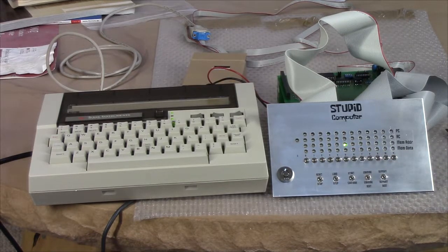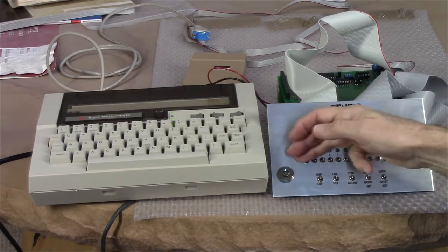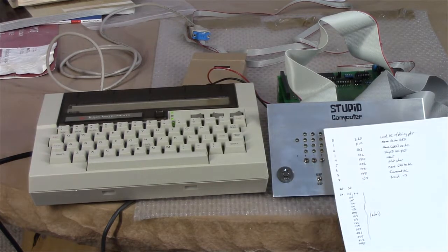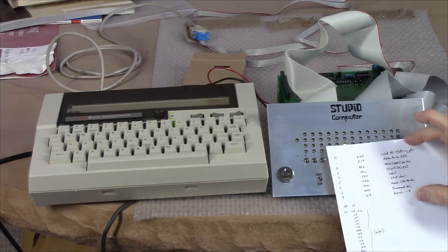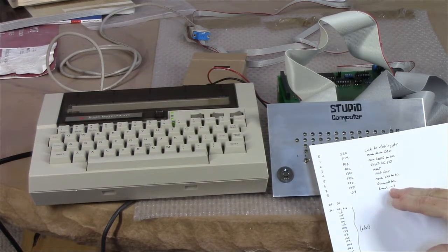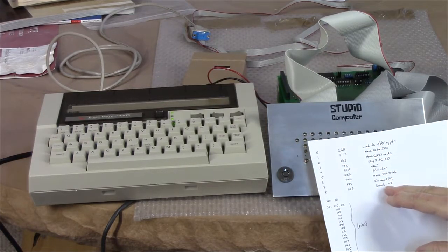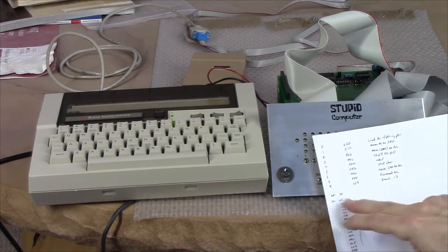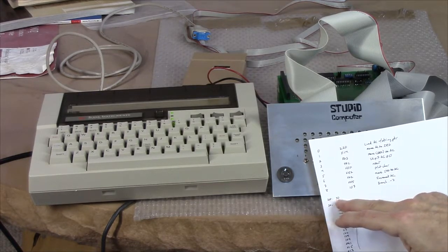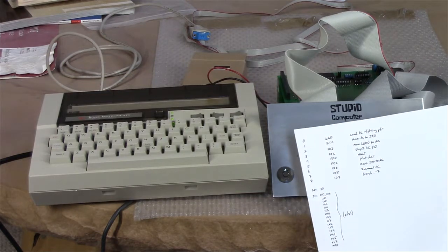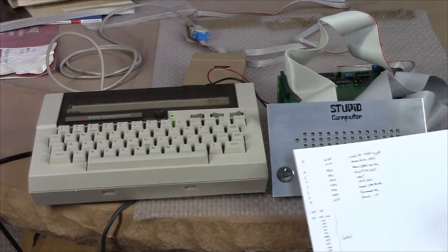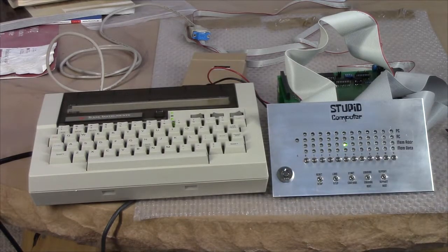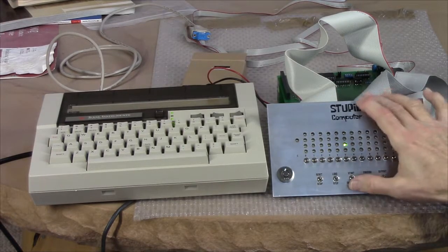Okay, so this starts at location 0. This code, by the way, of course, the code itself is relocatable because the only branch is a relative branch, and the fixed address is the pointer to the data and where the data sits. But I could have put this code anywhere in memory. I decided to put it at 0